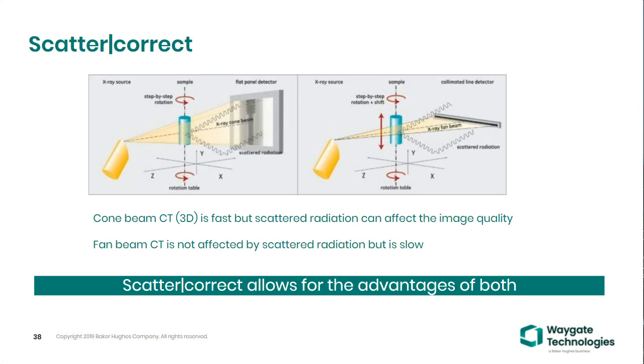Again, for you guys that aren't familiar with this technology, typically you get better scatter properties with an LDA as you're only capturing the X-rays that are going straight through. With scatter correct technology, we're able to use an area detector. In this case, the active area ends up being about 13 by 13 after it gets shielded. We're able to take an image or images of the parts, 13 by 13 inches at a time, versus a 0.5 millimeter or 1 millimeter at a time, which allows for significant savings in scan time that we talked about at the beginning.